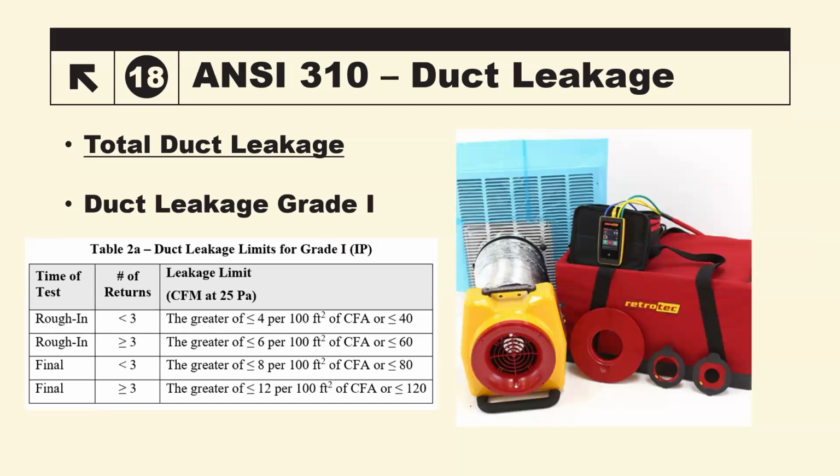So I'd like to jump in here real quick with a couple of comments to elaborate on some things. When it comes to these total duct leakage values, raters that are going out and doing these tests, I believe they're now required that the inside air handler has to be installed. So they can't test supply side and then the return side. They have to test the entire system. So the equipment actually has to be installed at the time that they do the test.